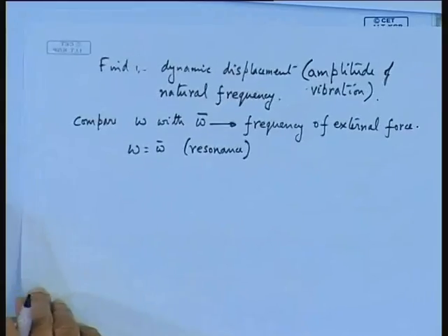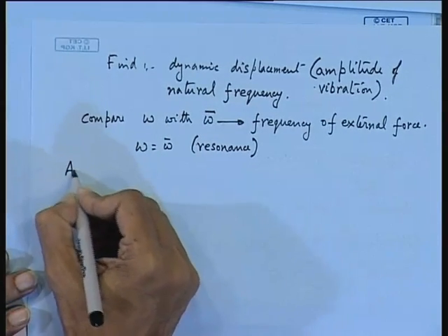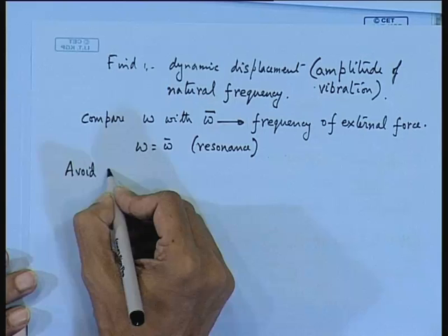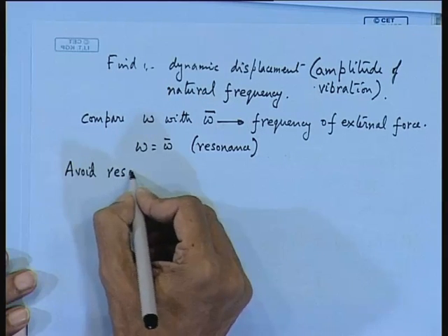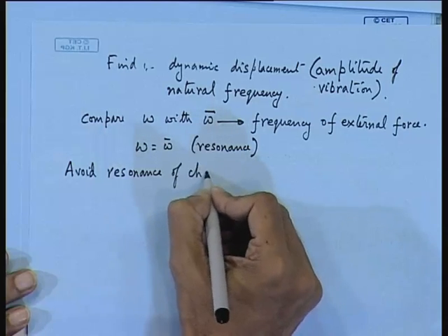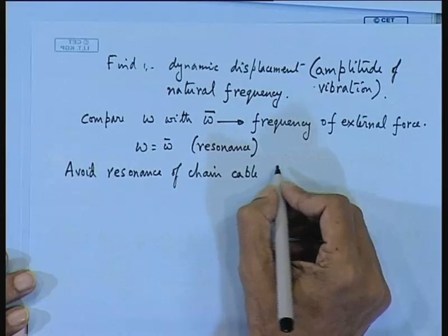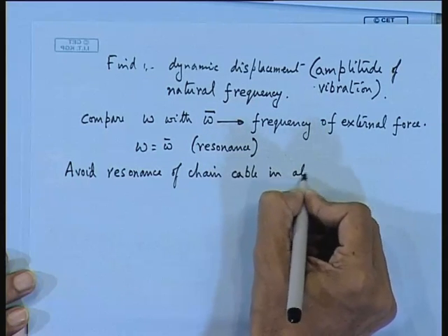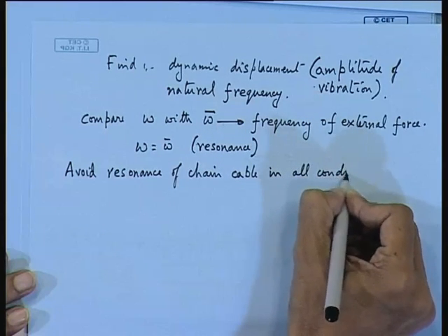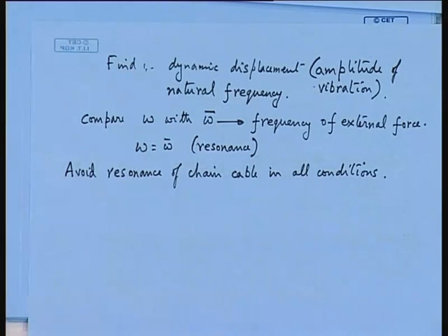So, now you have to avoid resonance of the line. So, avoid resonance of the cable, of the chain cable, in all conditions. In all conditions, remember this, your system should not have resonance with external force.